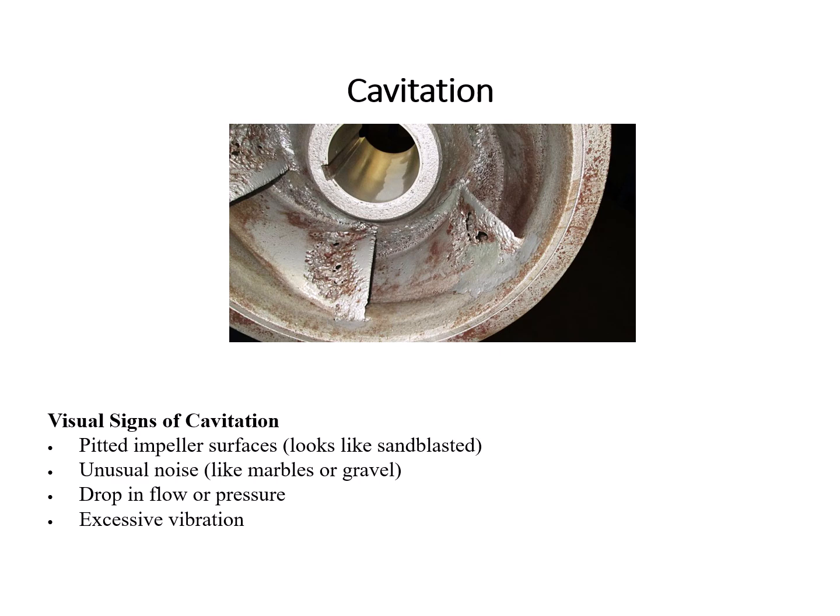A high drop of pressure will happen, and excessive vibration, because now the wheel will not be balanced, so it will be in a vibrating mode. So we always try to avoid cavitation as much as possible, so we will not lose our pump.